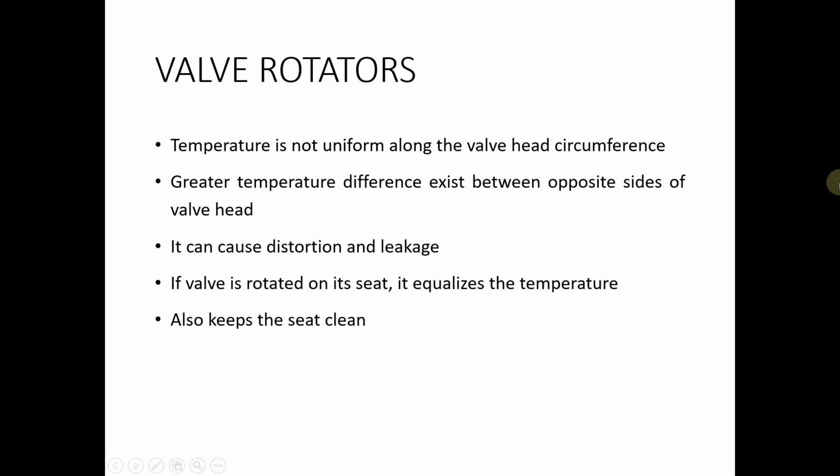We also have a component known as valve rotators, which are used to rotate the valves automatically. I had mentioned very earlier that we need to keep the temperatures uniform across the cross section of the valve head. In order to cool the valves, particularly the exhaust valve, before the next cycle, we make use of valve rotators.